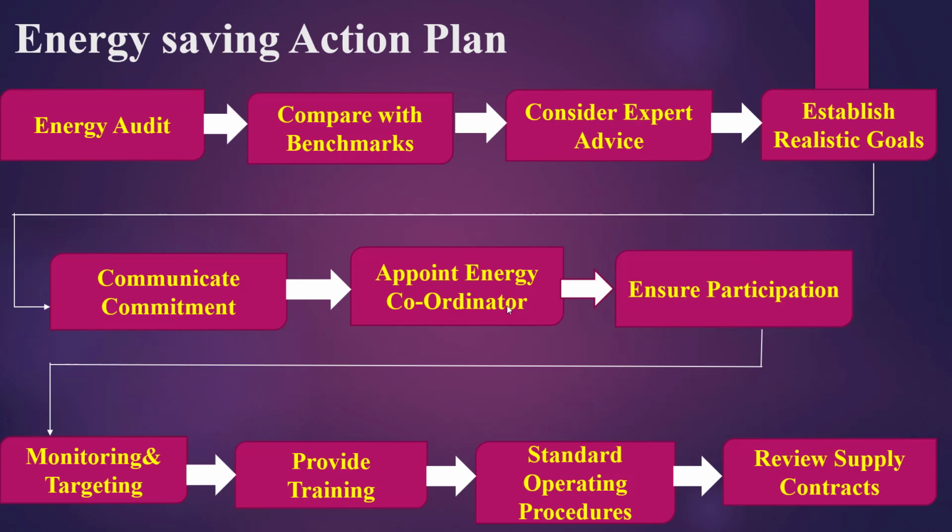It should be remembered, however, that if M&T systems are to be implemented successfully and their potential benefits achieved, it is essential that operators understand the system fully, rather than relying on outside consultants. Input consumption data is reliable, and not incomplete or late. Outputs are displayed in various graphic formats, not just columns of numbers, which are comprehensible to senior managers, energy managers, and staff. Reduction targets are realistic, rather than arbitrary, with adjustments for changes in equipment, etc. Excess energy use is flagged quickly and investigated rapidly by appropriate staff.